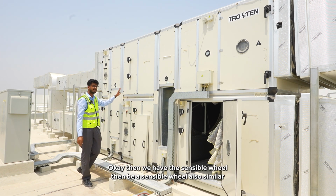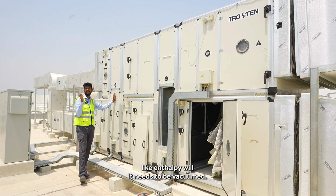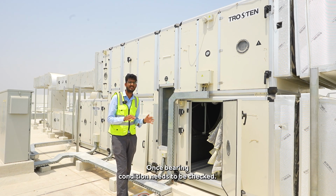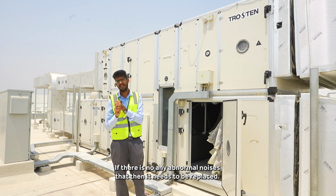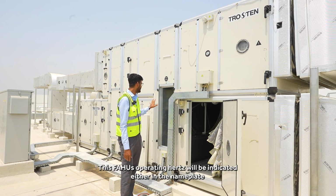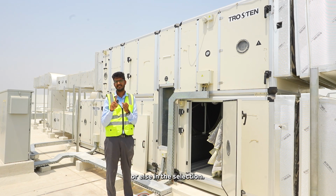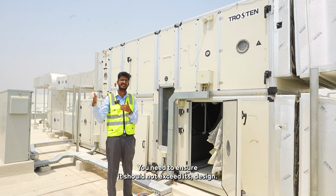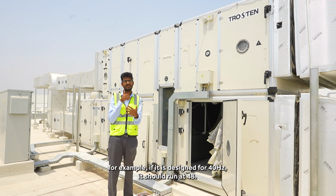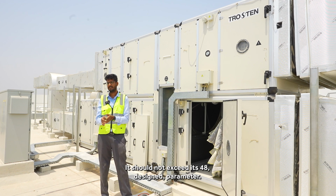Then we have the sensible wheel, which, similar to the enthalpy wheel, needs to be vacuumed. Then we have the fan motor: once a year or once every 2 years, the bearing condition needs to be checked. If there is any abnormal noise, then it needs to be replaced. And one more thing, the FAHU's operating hertz will be indicated either on the nameplate or in the selection. You need to ensure it does not exceed its design hertz. For example, if it is designed for 40 hertz, it should run at 40 hertz. It should not exceed its 40 hertz designed parameter.